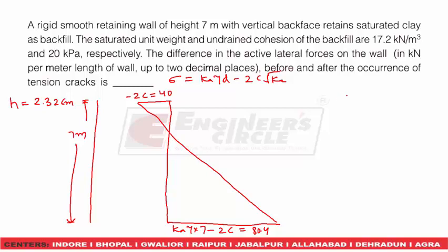Now once the tension crack gets developed, the contact of soil and retaining wall will not be there. So up to this height there will be no contact and hence no development of earth pressure.